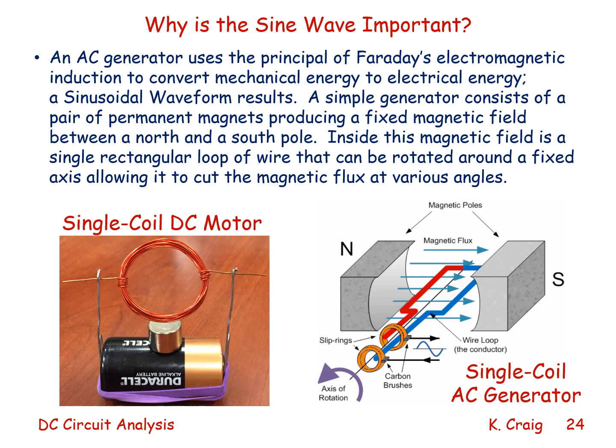I've included at the bottom left a picture of a single coil DC motor. It consists of a battery, 2 paper clips, a neodymium boron magnet, and a rotor consisting of magnet wire wrapped in multiple loops with 2 ends sticking out that form the shaft of the rotor and is supported by the 2 paper clips.